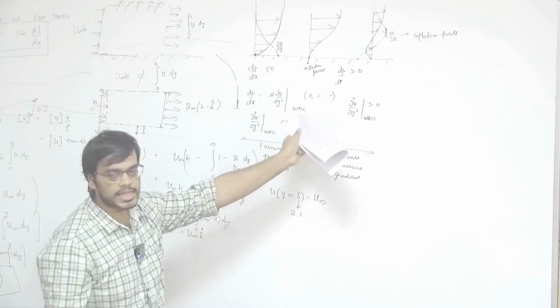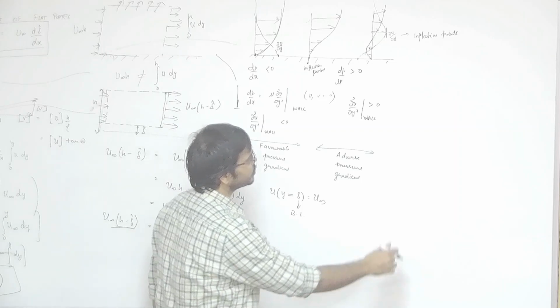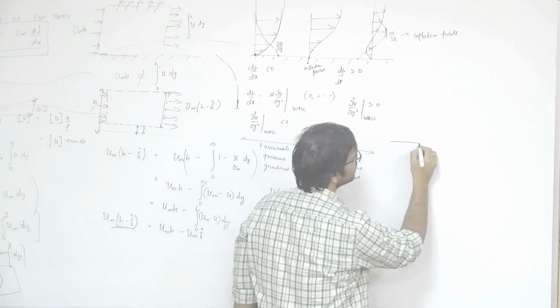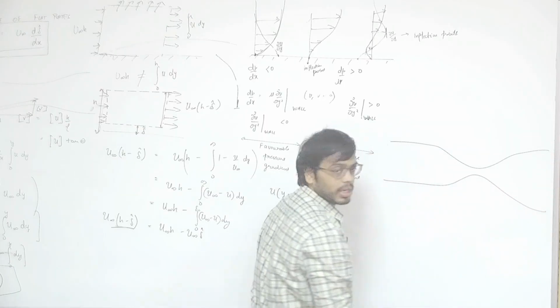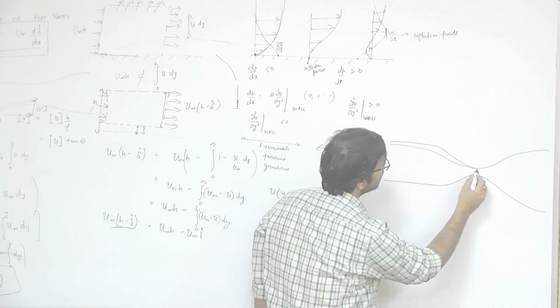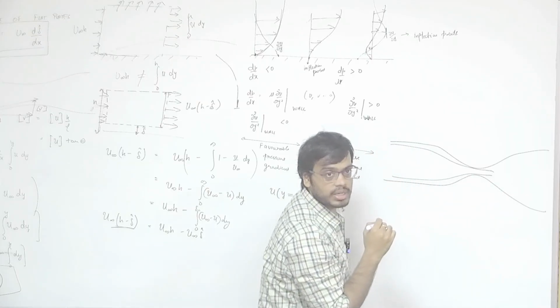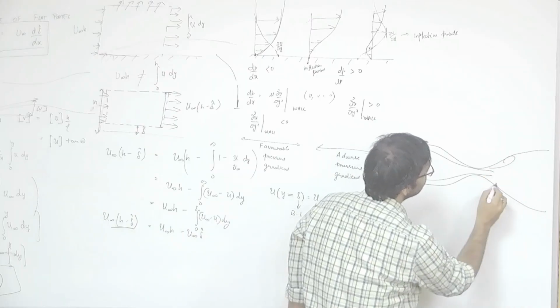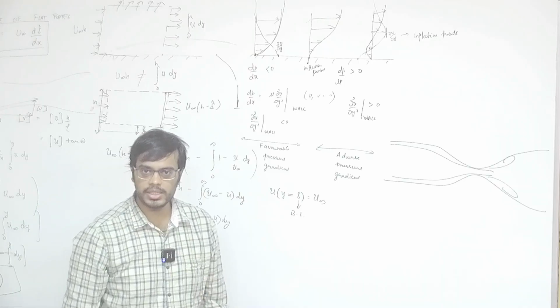You have actually seen this kind of phenomena in your undergraduate fluid mechanics courses, where let us say you were discussing the venturi meter. When you looked at the venturi meter, you have flow coming here, and then you have some region where you have the minimum area, called the vena contracta, and you were told that there are circulation regions here. What do those circulation regions mean?